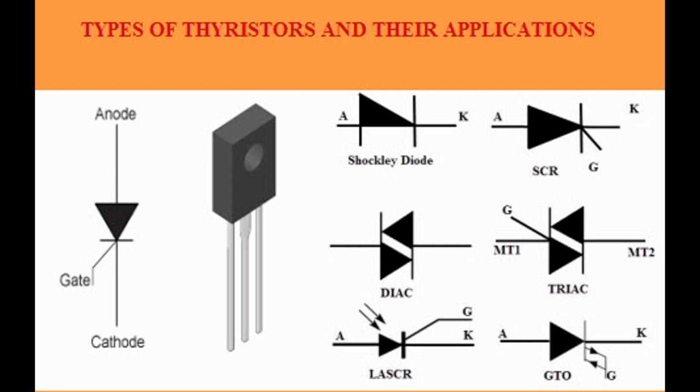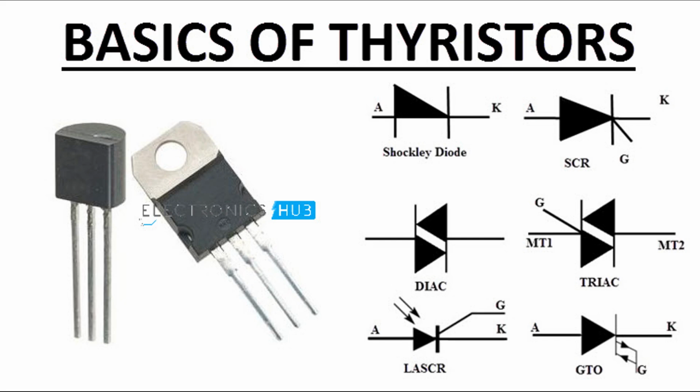Key characteristics. Bidirectional gate control, can be turned on with a positive gate current and turned off with a negative gate current. High voltage and current ratings, suitable for high-power applications. Moderate switching speed, faster than traditional SCRs, but slower than some other semiconductor devices like IGBTs. High dV/dt capability, able to handle high rates of voltage change without unintentionally turning on.